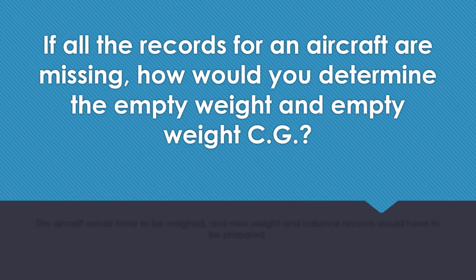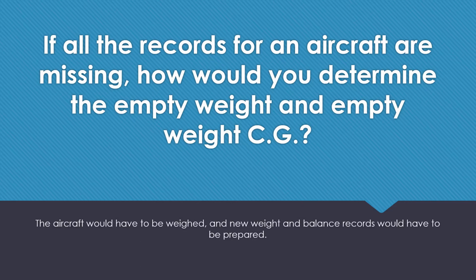If all the records for an aircraft are missing, how would you determine the empty weight and empty weight center of gravity? The aircraft would have to be weighed, and a new weight and balance record would have to be prepared.